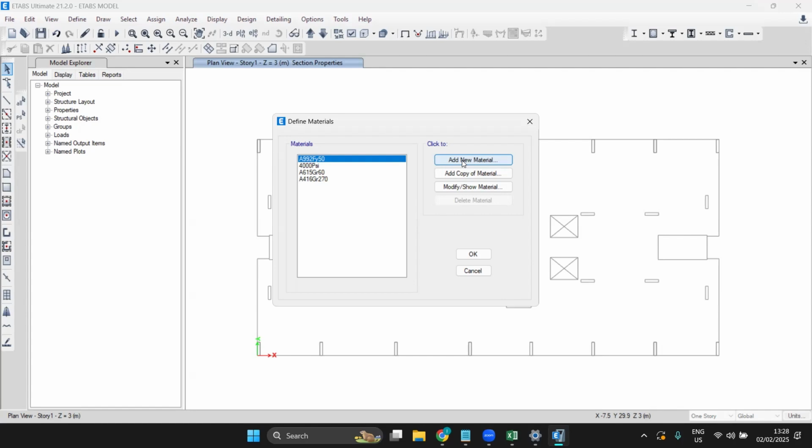For the basement, you need to take the footprint. I can help you with the footprint. The one which you extracted, the origin point for the typical floor, 0, 0. Take the basement footprint and keep it over the same origin, because you use the same origin. Keep the footprint, and then delete the typical floor. If you import this basement line, it will be exactly in position. You understand what I'm trying to say? You get it, right?